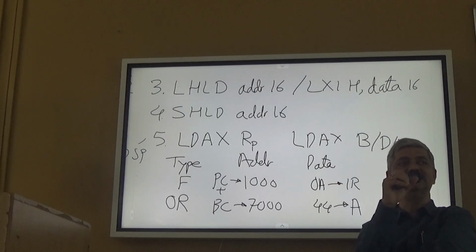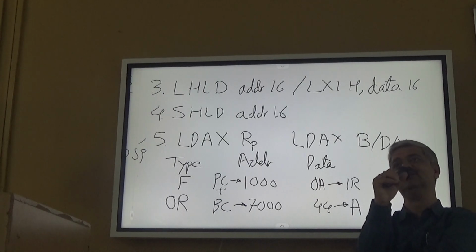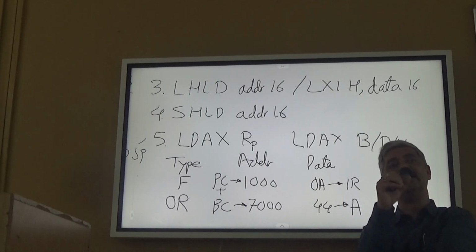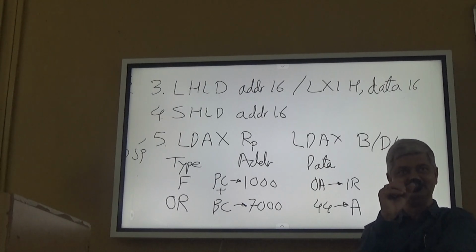So the instruction to bring the contents of the external memory location whose address is given in the HL pair into the accumulator is already there in MOV A, M. So the HL register can be used for a wide range or variety of instructions which deal with the data stored in memory at a location whose address is in the HL pair. So this would be redundancy.